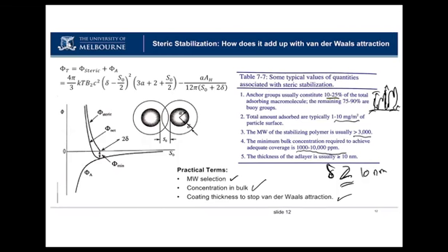One of the examples of this is wastewater treatment, where you have a lot of dissolved particulate solids, and they're stabilized by biological polymers, and so no matter how long you let them settle, they never flocculate because they're so stable from steric stabilization. So steric stabilization, great when you want it, terrible when you don't. So steric stabilization is a very awesome way to have a repulsive interaction between particles.